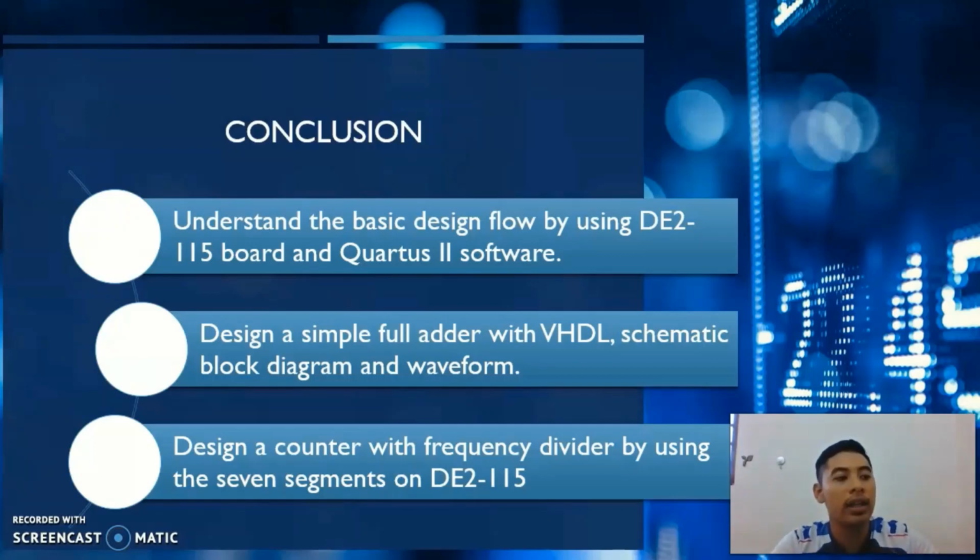What we get from this lab is that we can understand the basic design flow using the DE2-115 board and Quartus II software. We are also able to design a simple full adder with VHDL, schematic block diagram and waveform. And lastly, we can design a counter with a frequency divider using the 7-segment display on the DE2-115 board.